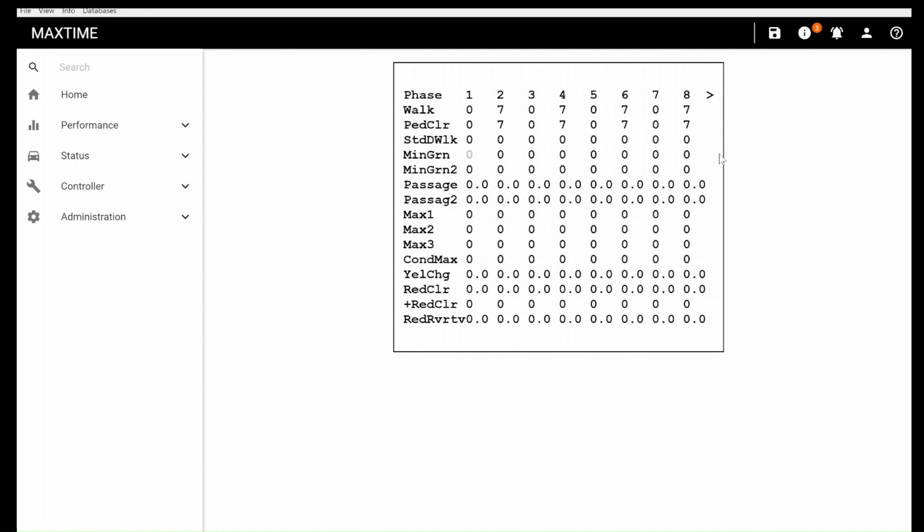Now I need to put min green times in since we're doing this as emulated. Let's say our left turn's at 4 seconds, 20 seconds on the main line, 4 here. Let's give them 15 for 4 and 8. So this one would be 4. This one would be 20. Normally you wouldn't do this.